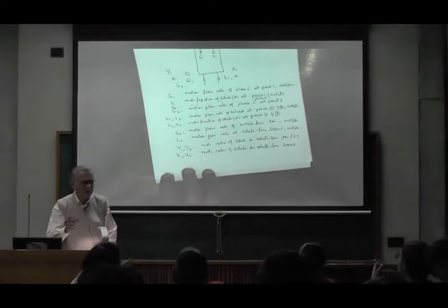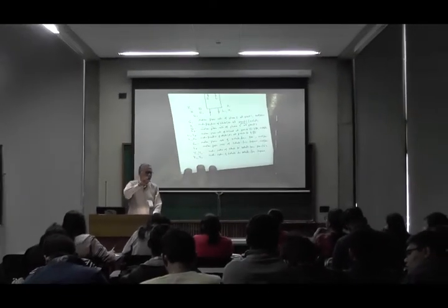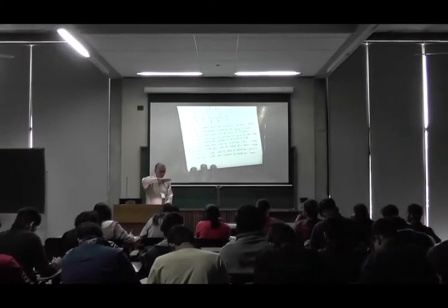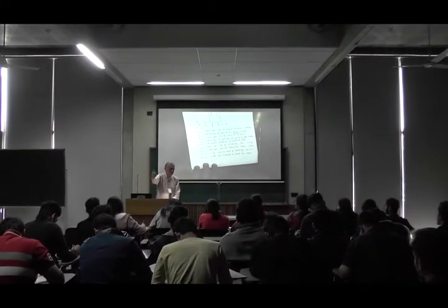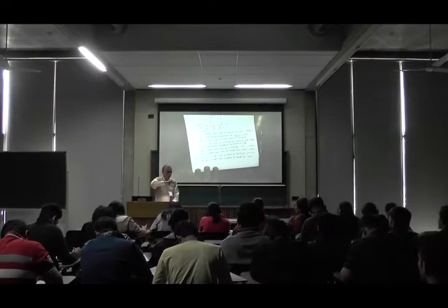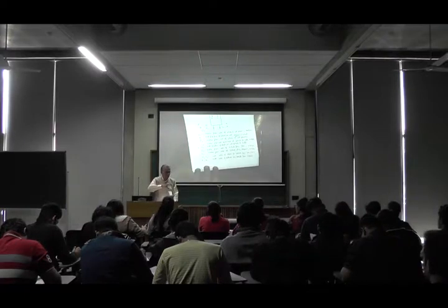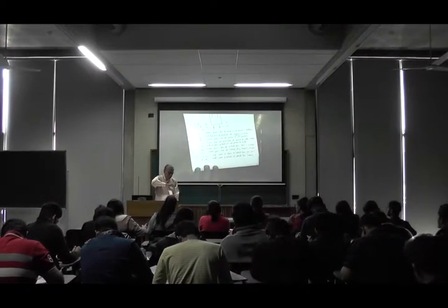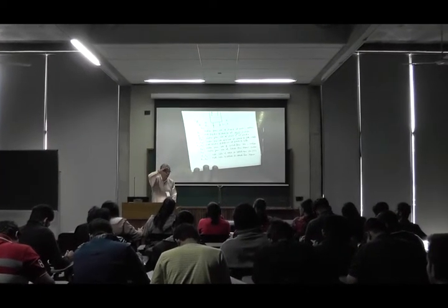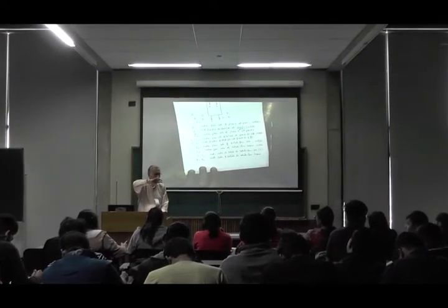A is being transferred, so the moles of total gas decrease. Supposing we have air containing ammonia coming in, and it is being absorbed in water. We are assuming that air doesn't absorb in water. So the flow rate of the total air plus ammonia going up will change, but the flow rate of the air part will not change.